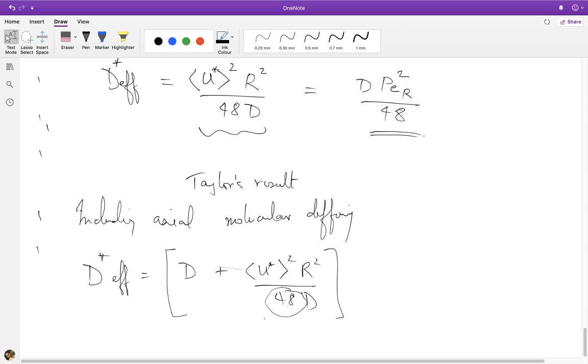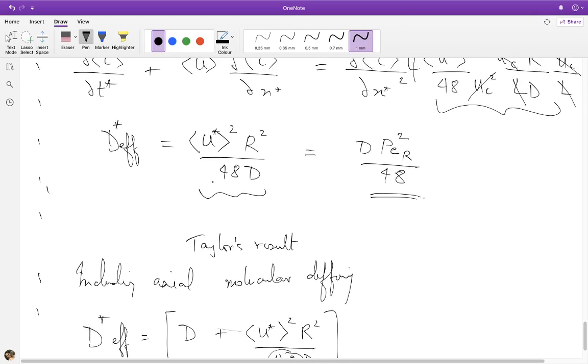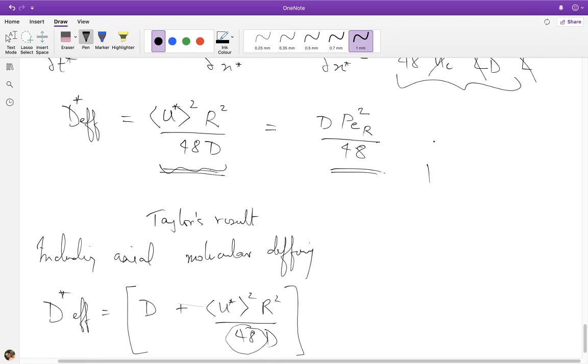So before we conclude, it's useful now to try and understand physically why it is that we have this diffusivity sitting in the denominator of this effective dispersion coefficient, right here. We saw in the numerical experiment in Fluent that if we make this molecular diffusivity large, the axial dispersion decreases. The theory predicts that, and so the question is why.